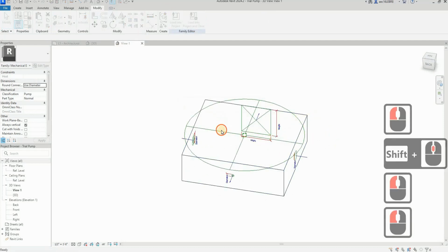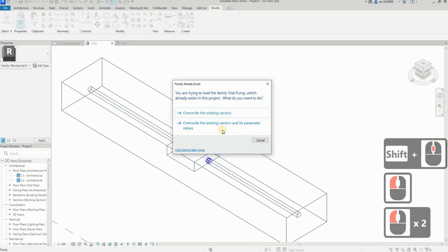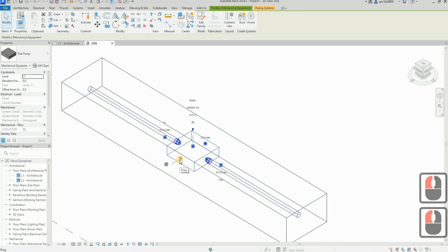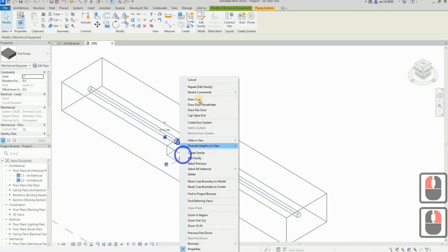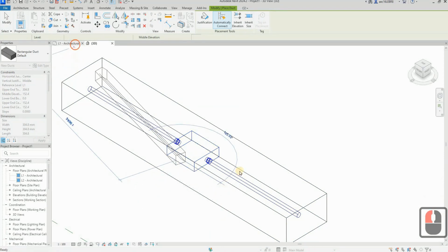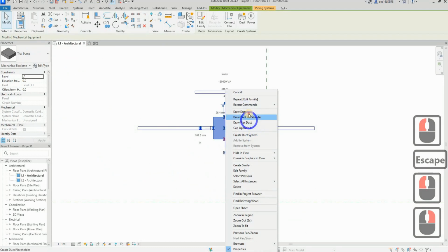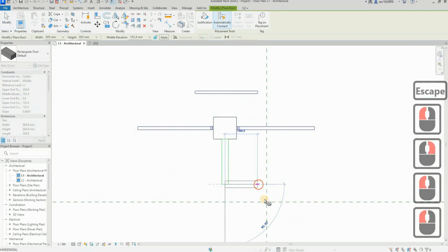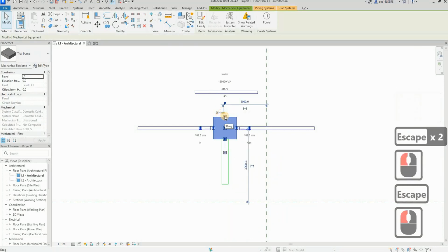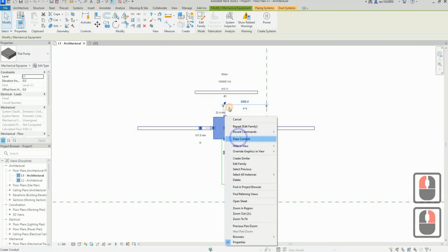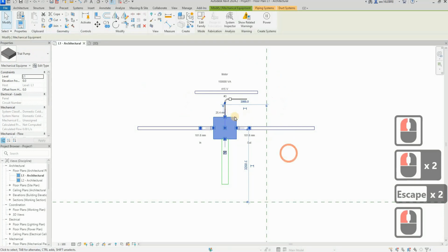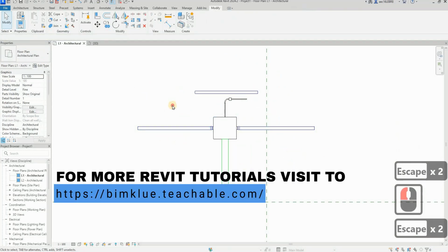Let's look inside, see what happened. So click on here. You have a duct connector over here. You can actually draw a duct from here. Draw aircon duct from here. Okay, this is the aircon duct. If you have a conduit over here, you can also start to draw conduit. Okay. So that's the function of connectors basically.